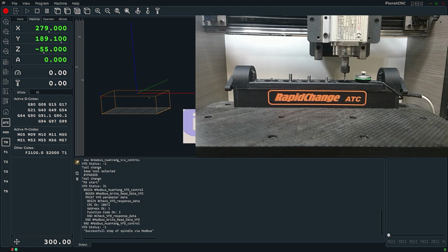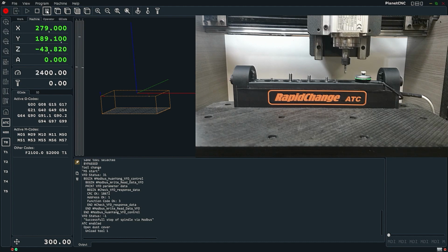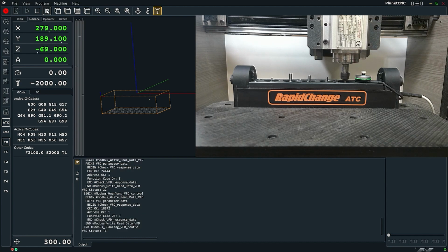And now remember I selected the message and pause. So the message comes up, change tool 1 to tool 0. Okay. Now I've also got the pause selected, so it starts out paused. Click that. And now this should drop off tool 1 if we've done everything right. Looking good so far.